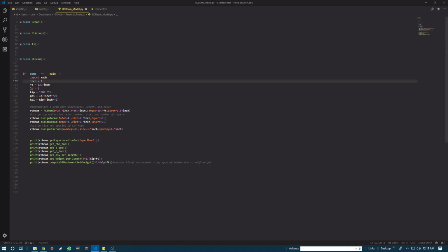At the beginning here, I'm defining my units. If you guys are familiar with this approach to defining units, what you can do is tag your dimensions with base units. So inch would be equal to 1, pound equal to 1, which basically means when you run all of your calculations and you have all your dimensions in it, at the end everything's going to be in units of inch and pounds, unless you do an inversion like down here I'm showing.